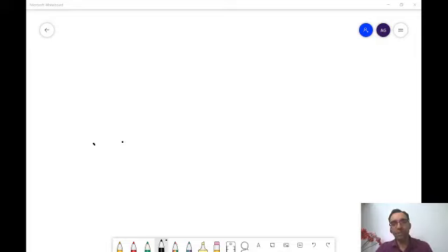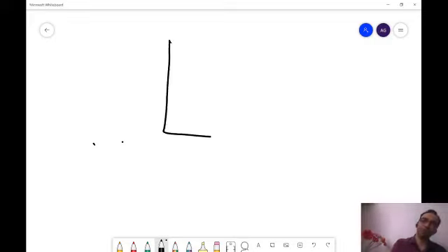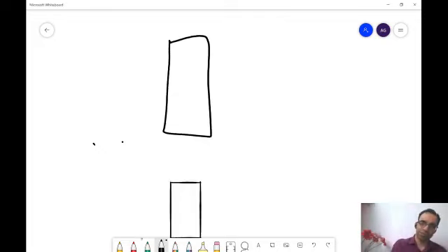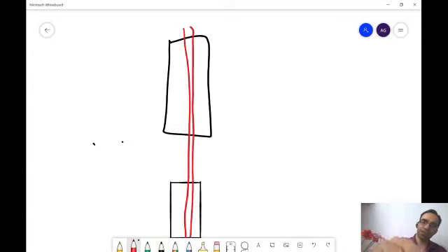So yeah, let me take you to that. Raghav, what you're asking is, if I try to answer Vaishnav's question: okay, I have 7 microns of PMOS and 5 microns of NMOS, and I have to draw them, how do I draw them? So until now, possibly what you guys are doing is you are saying, okay, I will make one big PMOS over here, one big NMOS over here, and I will make a poly between them. And this is how my thing would look.